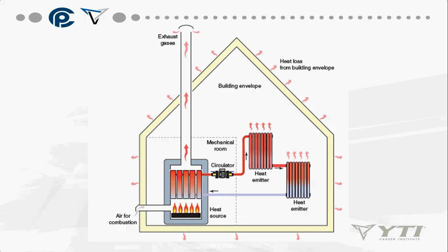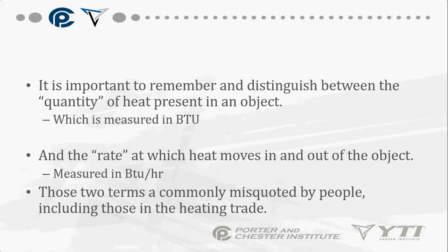It's good information to know. How well are my walls insulated? How well is my ceiling insulated? Okay, if you have poor insulation, you're going to have a greater heat transfer, greater heat loss. Okay, which raises the boiler output that I'm going to need because I have to compensate for what I'm losing, right? That's what makes a person feel comfortable, is that compensation of whatever their body's losing to what I have to put back into the space.